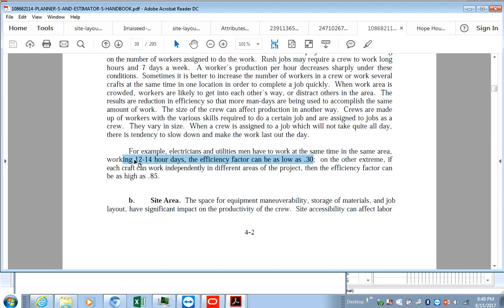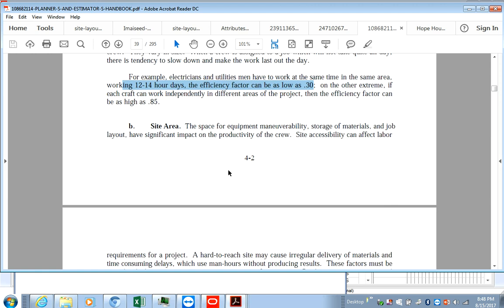As opposed to having men working 12 to 14 hours, how many breaks will these guys take? When will fatigue set in? How much productivity will you get out of them? This is where you can say, for those who perform their job specifically and are skilled, that after 6 or 7 hours their productivity levels start to drop from 80% to 40 or 50%. You can apply all of those techniques into your resource estimation.